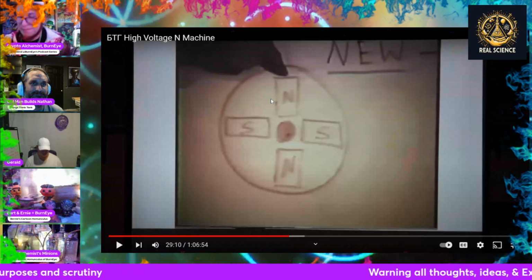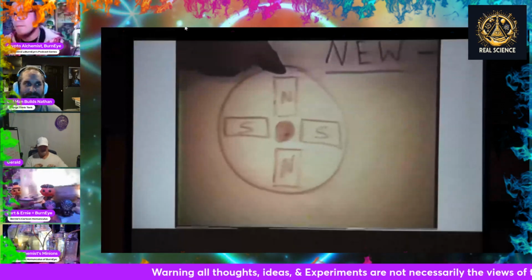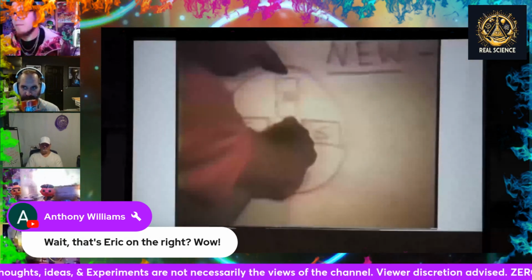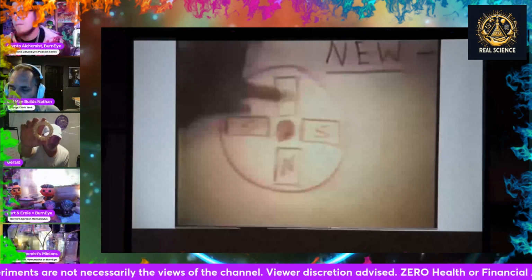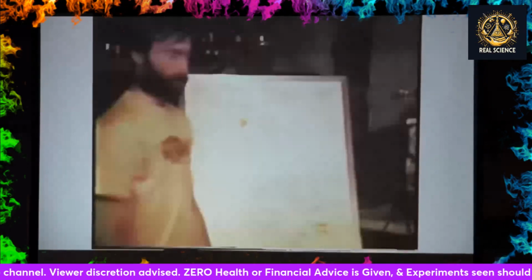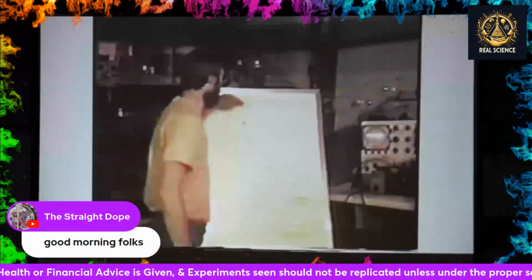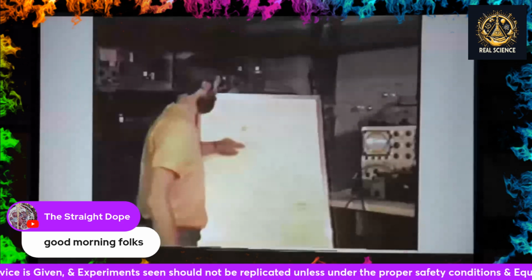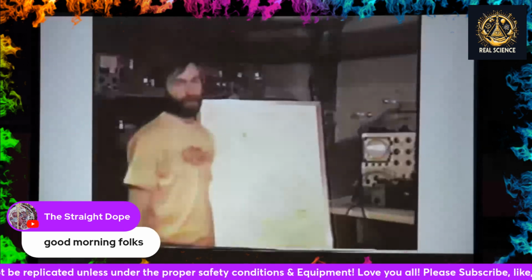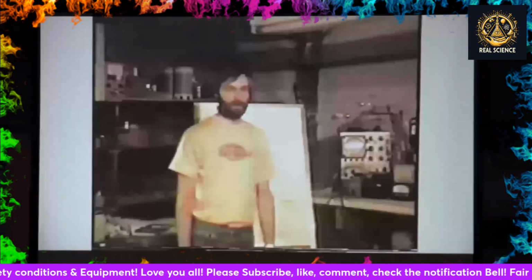Riding on the disc out at this location, so that as the different pole faces move past between these two brushes, they produce EMFs in opposite directions, as would be expected. What was interesting about this is that it produces any EMF at all, because all of the points on the shaft that would be producing these things are in direct short circuit with each other at an extremely low resistance. Peter, is the frequency determined by the RPM? Yes, it's direct. It varies directly,